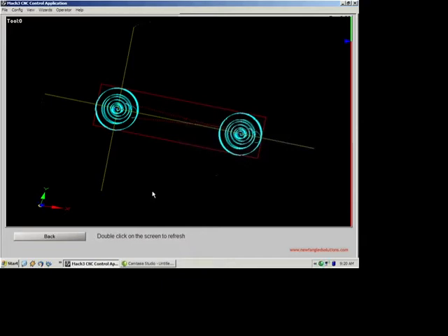This P parameter will be right on the line before it starts cutting this, so it would be like a G41 P and the radius of the tool. So as you adjust that radius, you can adjust the diameter of your part.